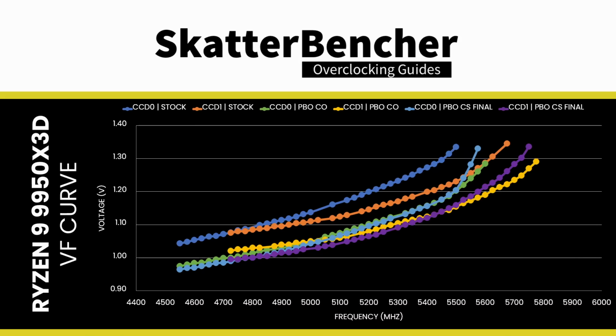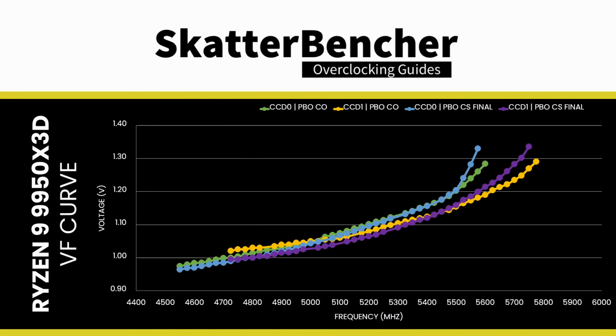Here's the resulting curve with a low and medium Curve Shaper of -30, a high frequency Curve Shaper of -25, and a max frequency Curve Shaper of -10. We can compare it with the curve optimized curve from OC strategy number 2. We can clearly see the trade-off between the extended frequency range and the use of less aggressive undervolting at the upper end of the curve. However, we squeeze a little more frequency at the lower end of the curve because of the more aggressive undervolt with Curve Shaper.